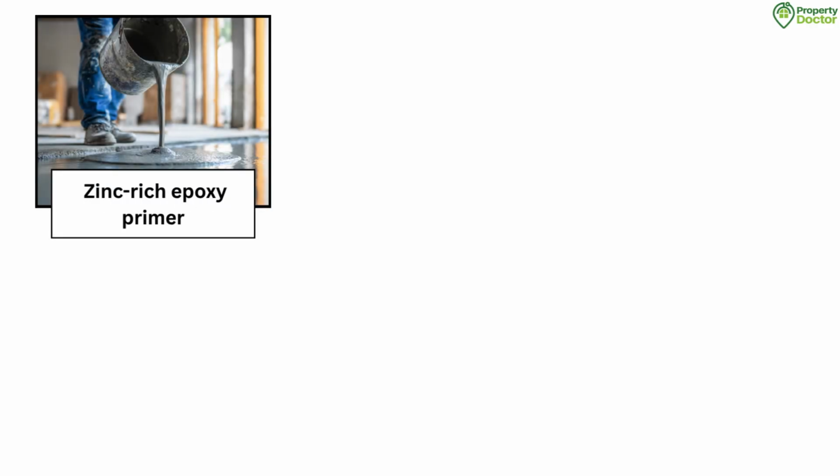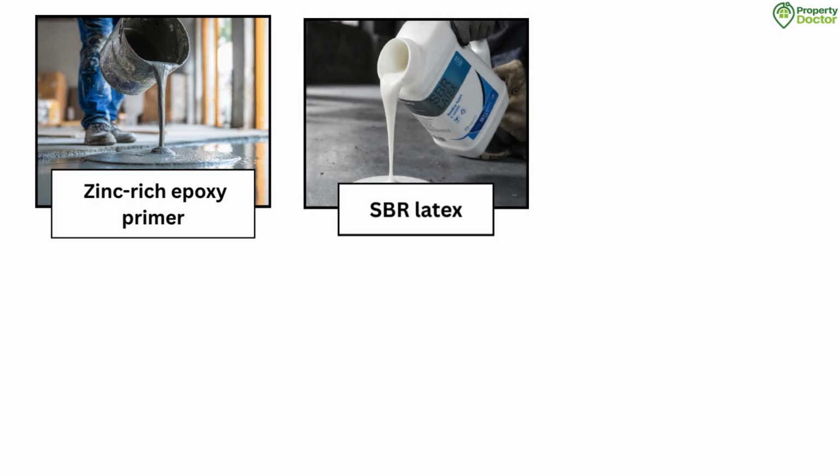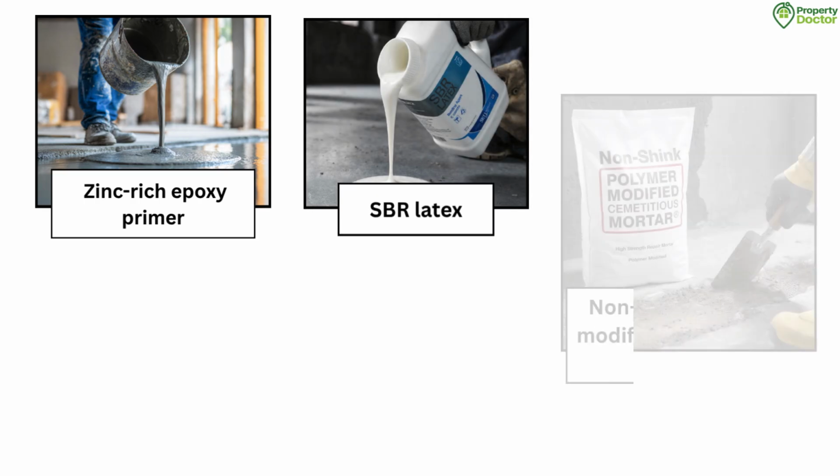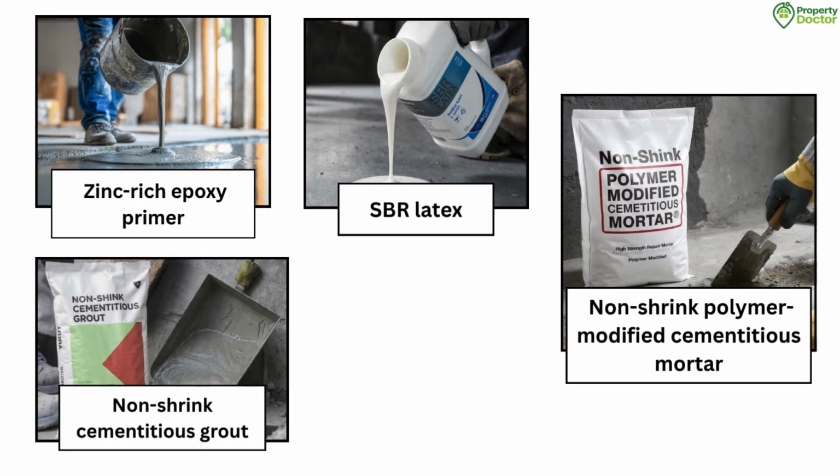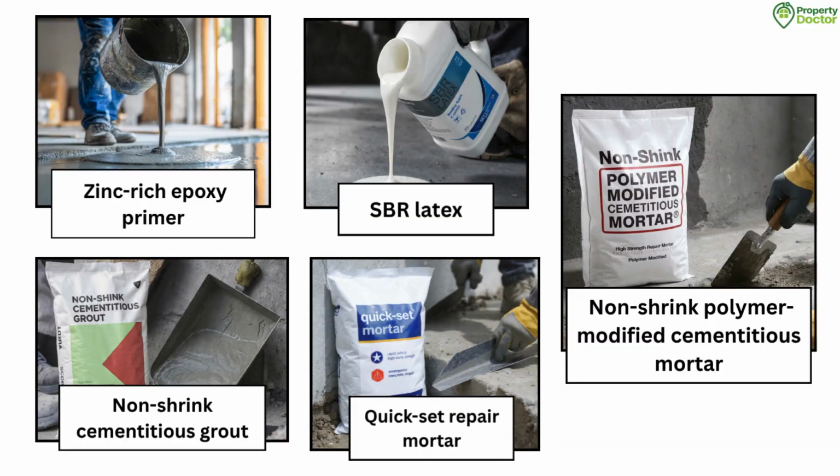Chemicals and materials needed: zinc-rich epoxy primer, SBR latex or styrene butadiene rubber slurry, non-shrink polymer modified cementitious mortar, non-shrink cementitious grout, quick-set repair mortar.